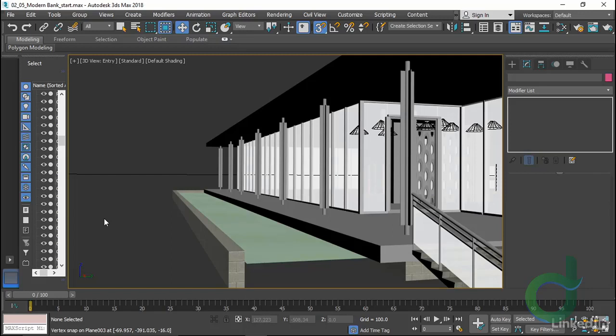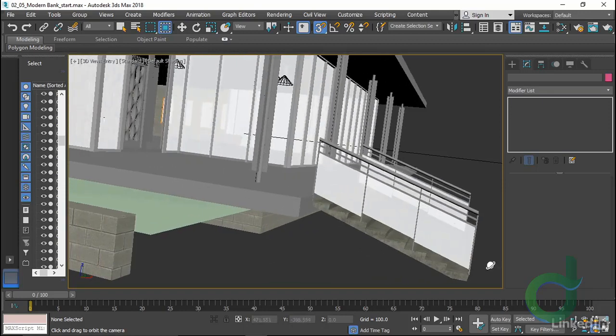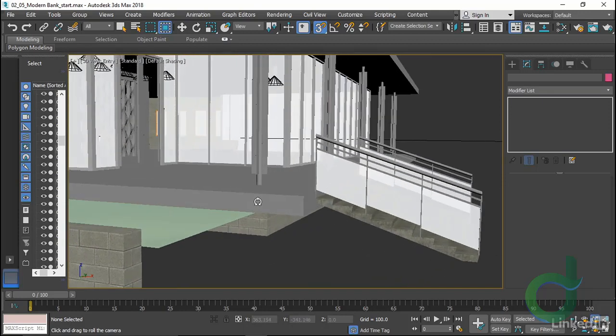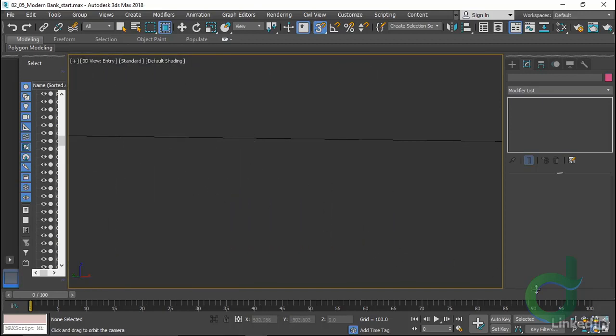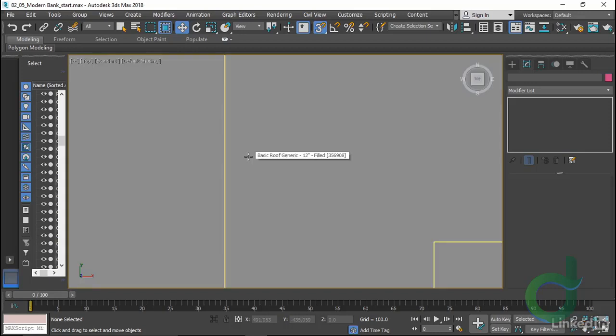Now, if you need, you can use this technique to make much greater hills, really adding in some variation. But for this, I just want it to be a planting bed, and so it's going to be pretty flat within a range, not exactly flat, which looks odd. I'll orbit around, use the roll tool to reset my camera, orbit around by holding Shift, dolly back, and check it out. If you find you lose your camera like I just did, I have no idea where I am.